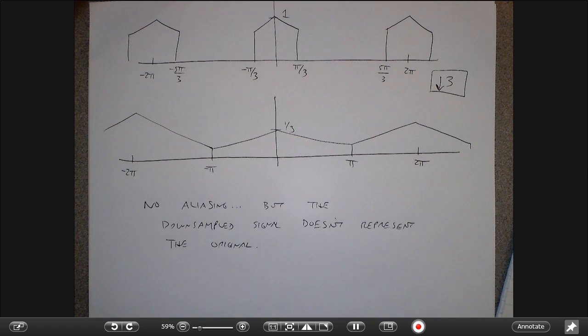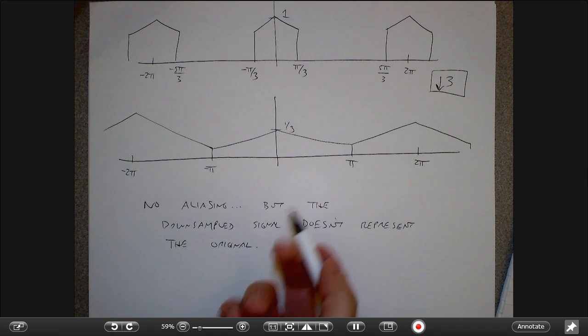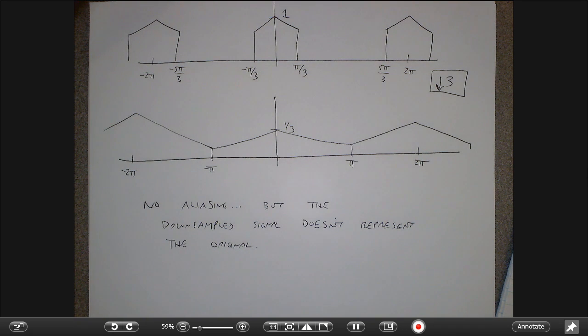But as long as there's not a lot of high frequency content, I may be able to get away with this for a while. As you noticed, if I really cranked up the downsampling factor, ultimately I got something that was too garbled, because all the stuff overlapped into the low frequency band. I could have tried to pre-filter that signal with a low-pass filter. Then what I would get basically would be a reconstructed low-pass version of the original sound, right? So in some cases you may be able to get away with it, and in other cases you may not.